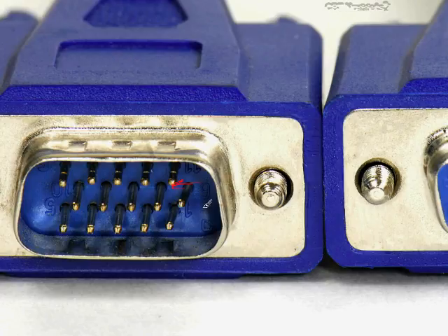Okay, and one thing that I want to tell you about is if you have any of these kinds of cables, whether it's VGA, serial, parallel, whatever, and you have some pin misalignment like that, an easy way to straighten that out is potentially with needle nose pliers. I generally tend to prefer a flat head jeweler's screwdriver, and I just exert a little bit of pressure in the opposite direction to push it back over where it was supposed to go.